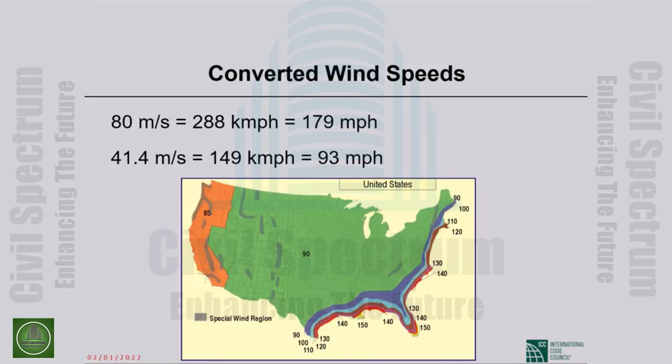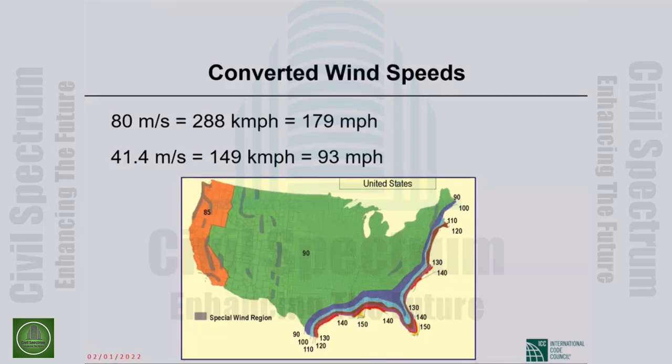And remember, always, pressure due to wind is proportional to the square of the velocity. So you go from 150 to 180, that is a sizable increase, but 150 squared to 180 squared is a much bigger increase. Okay, so I want you to appreciate that in parts of Bangladesh you have to design for extremely high design wind speeds, which will give you very high design forces to deal with in your structure.